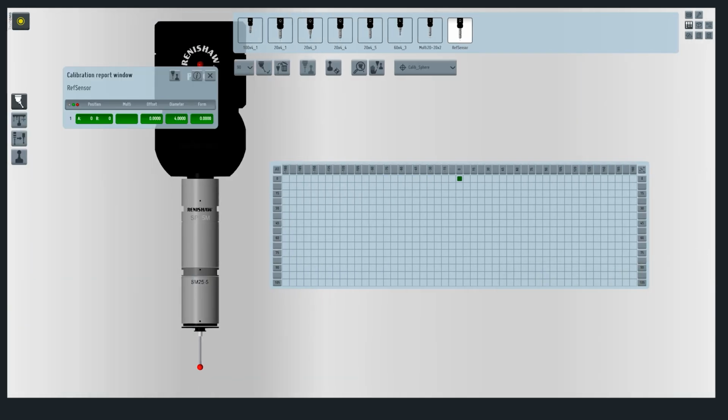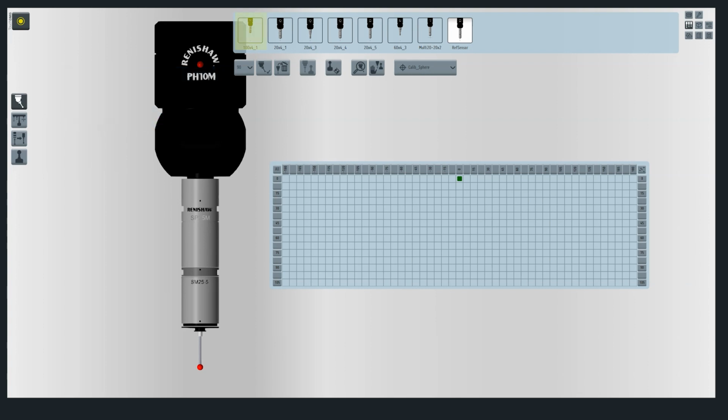In Calibration Report window, you can check the calibration results. Offset of localization position must be 0. With calibration object located, we can continue with the calibration of other position. Choose a probe assembled previously. To select the probe, use the right-click or hold the probe. Then select the option, Set Probe Assembly as Active. In this case, we have selected this probe.